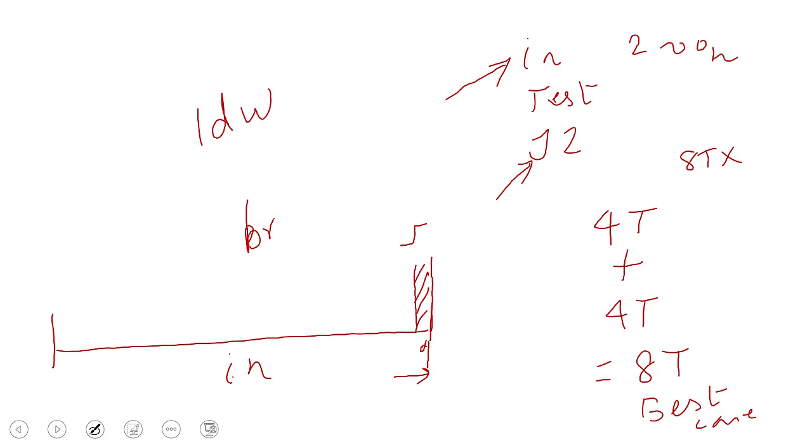So the codes between them are actually causing the polling latency. You can use single step mode while compiling. After you compile it, use the single step mode and see which instructions you are actually passing through, and that should give you the instructions which are responsible for the service.